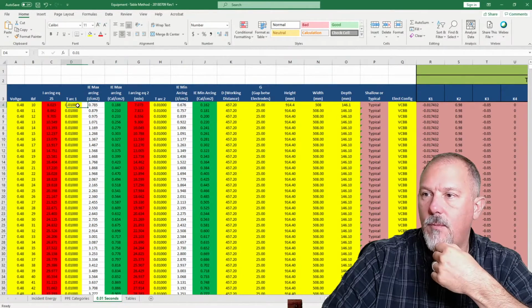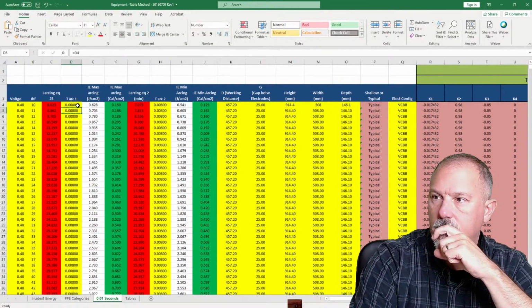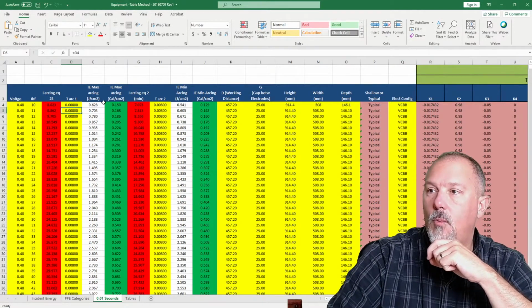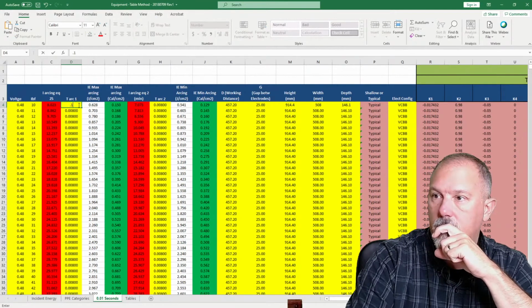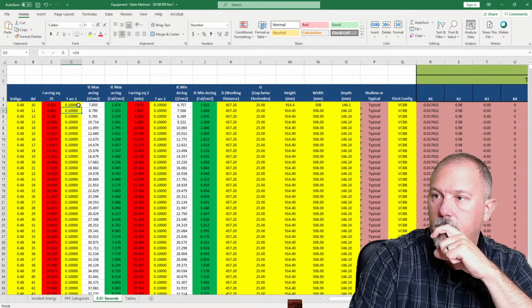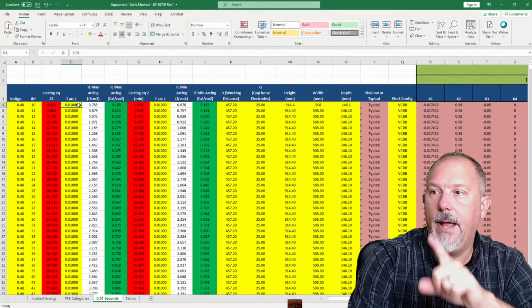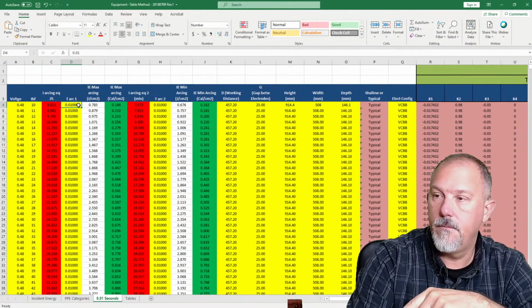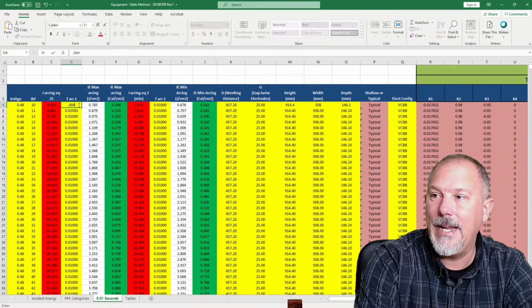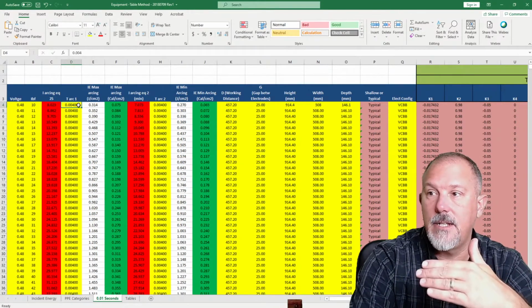Calories per centimeter squared. What if I change this to 0.008? There it is, 0.15. So I went from 0.01 seconds, let's go to 0.004. From 0.188 to 0.075. So I can reduce my incident energy considerably.